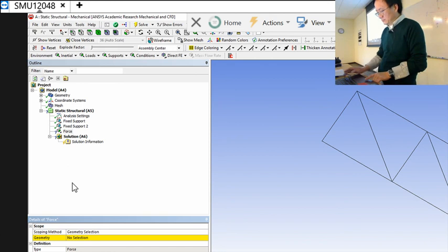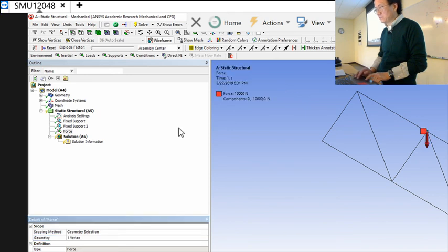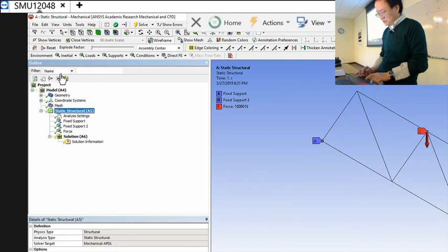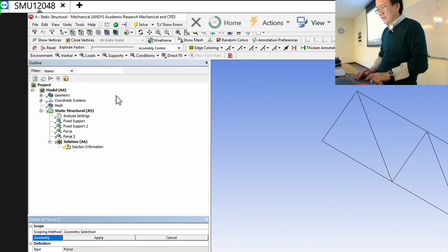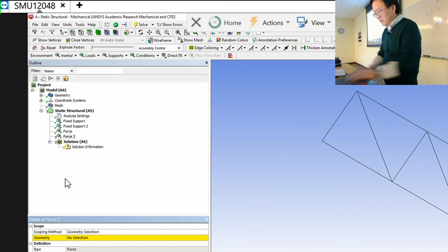Okay, enter. So now we do the selection, you still wait for the selection, and that's the point we selected. Now you say apply, and you see the force applied. Repeat this for the top left point. Apply a horizontal force. So go to Insert and Force. Again, use the components format. That will be in the x direction, 5,000 Newton. Enter.